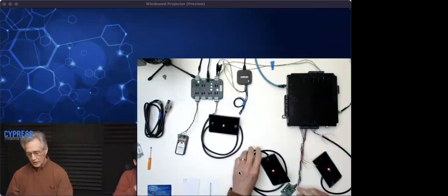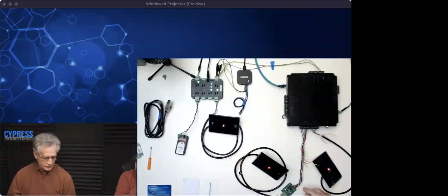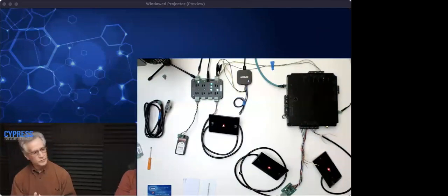All right. So yeah, that's an extremely good question. Now, your Wiegand wires, that's what's vulnerable. It could be just 3 inches of Wiegand wire hanging on the outside or the attack side of the door. That's what's vulnerable. If you have twisted pair OSDP running encryption, then it's not vulnerable anymore.